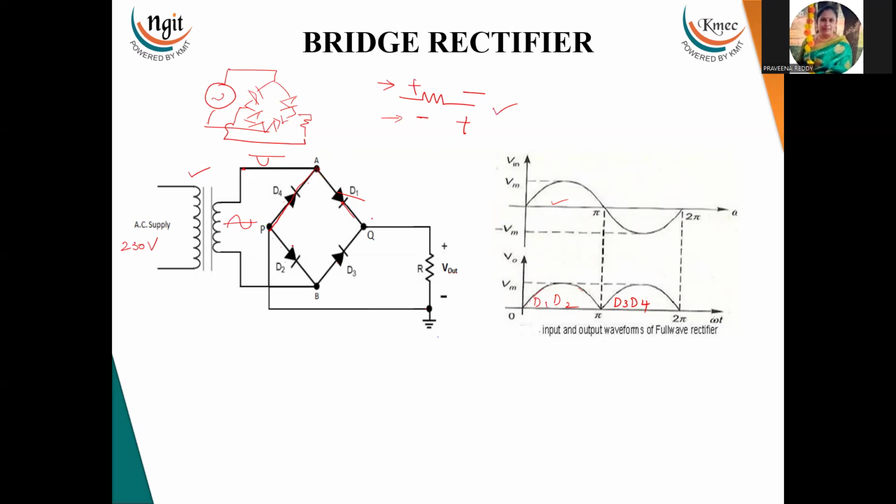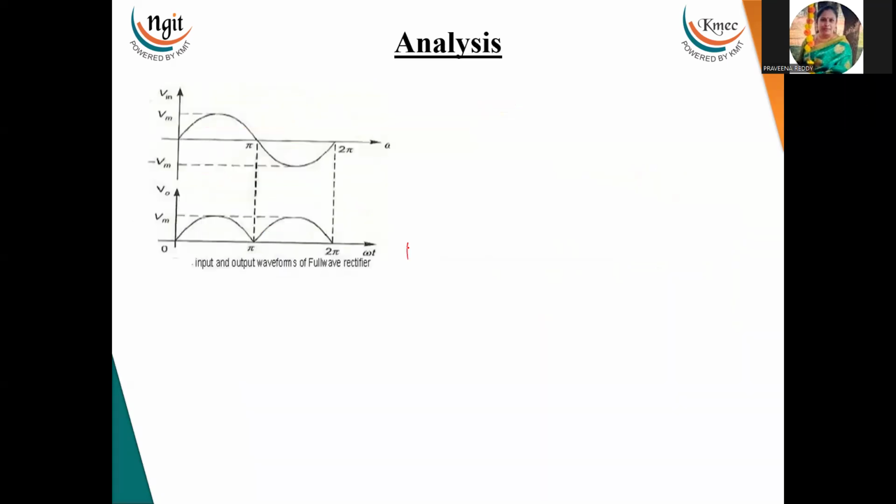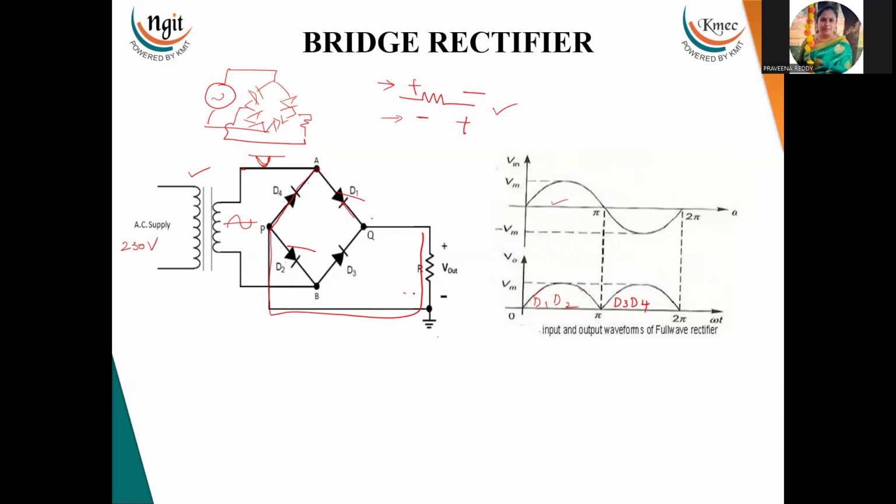And for this negative half cycle, again, D2 is reverse biased. So it will flow in this direction, and it is going up. But this is the negative cycle. Negative current is flowing up. So it makes first negative and next positive. It comes here and already diode D1 is reverse biased. So it will flow through diode D3 and go to the transformer.